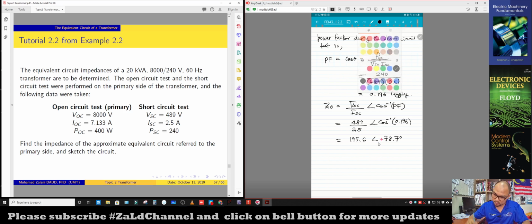The series impedance, this one we want to convert to rectangular form. I just keep the way we convert polar to rectangular, because you have learned it before. So this one becomes 38.4 plus J192.